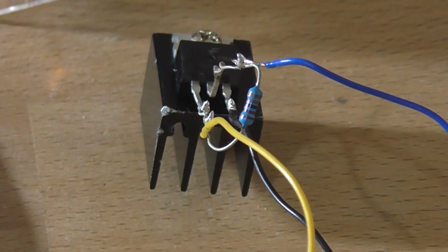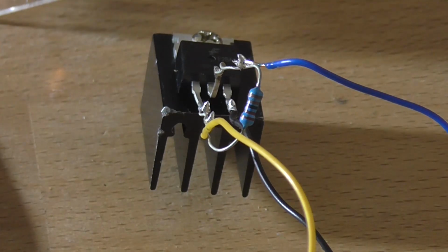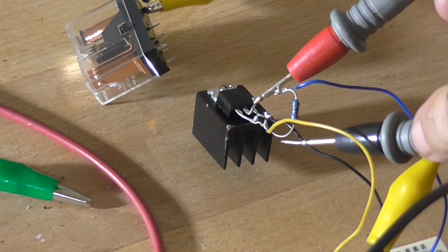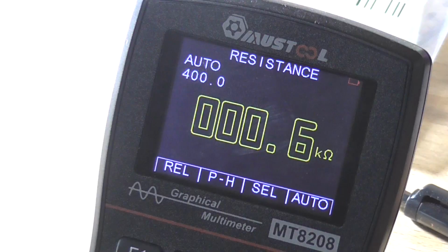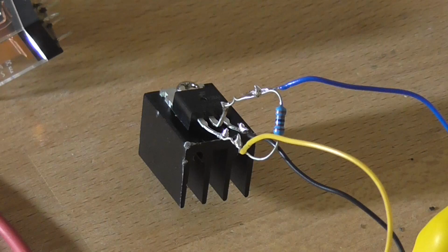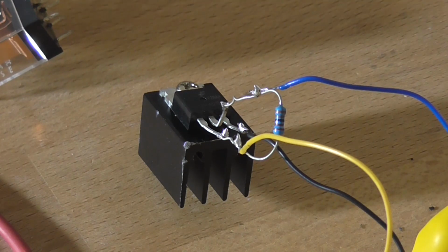I'm also using a TIP42C instead of a BD140. It doesn't really matter, it's a power transistor. I've got the base collector resistor, which is the 1.2K soldered across the transistor directly. So I need to see what I've done here. Oh, I see what I've done. Oops. I've mistakenly put a 2.2K base collector resistor across that transistor instead of a 1.2K.